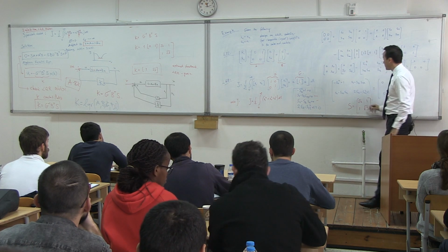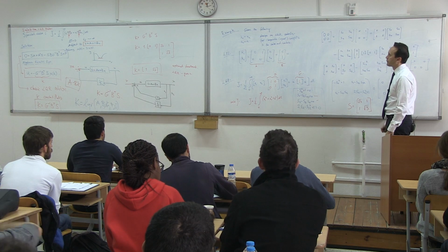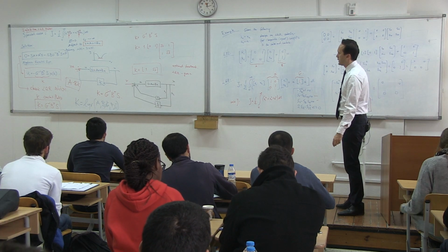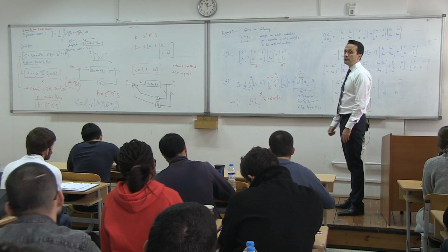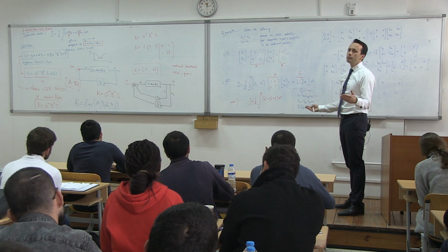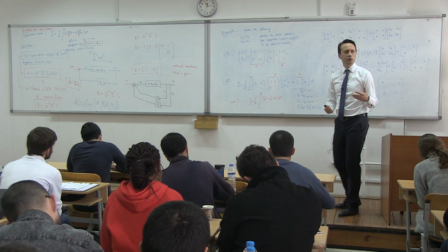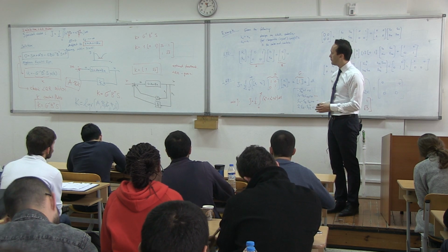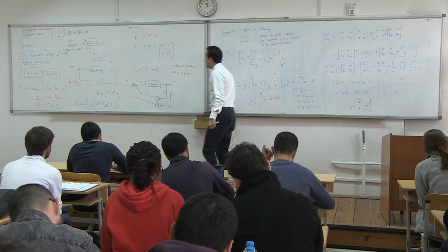But I can see this is a positive definite matrix right here because everything is positive, right? So naturally I would select this. So this is your optimal feedback gain. Now the question is, where did the eigenvalues move? I mean, we didn't really choose any eigenvalues. We don't have any desired eigenvalues. Where did the eigenvalues move? Now we can check this, of course. We need to look at the eigenvalues of A minus BK.